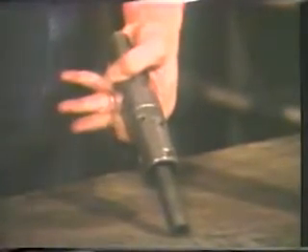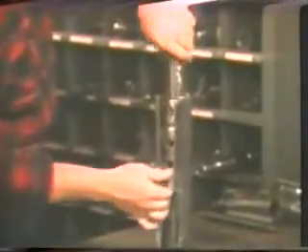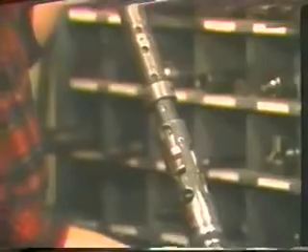Without the locator ring on the running tool, the lock may be run below the desired nipple and pulled up to it, allowing the up-facing locking dogs to locate the nipple. After locating the nipple, the same setting sequence is followed. Another running tool designed to run the S-lock is called the Model E running tool.